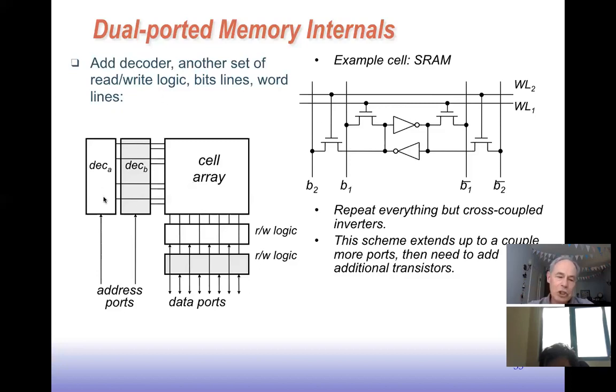So what this means then is we could have each decoder here have a different address, right? And so this grayed out decoder here is activating the lower word line, and the white decoder on the left is activating the upper word line, right? So each decoder could be activating a different row. So we can have more than one row activated at a time, but the values don't get confused because they're going to use different sets of bit lines.